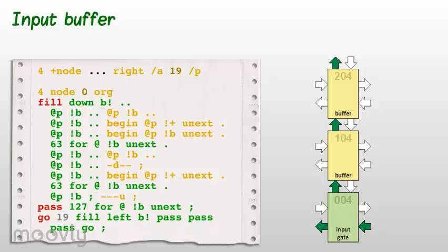It is worth noting that A register, which is used as pointer in both 104 and 204, is left with value 64 when the buffer is full. Due to rollover of address pointer in F18 computer, this address actually points to location 0 in RAM. This is the first data word stored there.